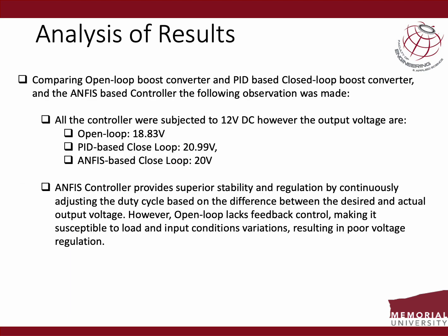Now, in terms of analysis of the results, both controllers were subjected to a 12-volt DC input. However, after the simulation, we realized that the open loop boost converter was giving us 18.83 volts, whereas the PID based boost converter was giving us 20.99, which is approximately 21 volts.